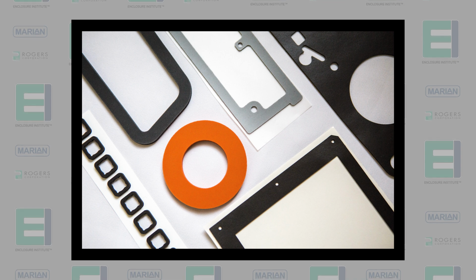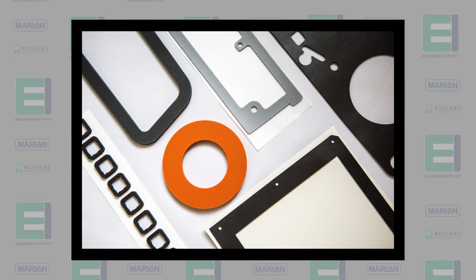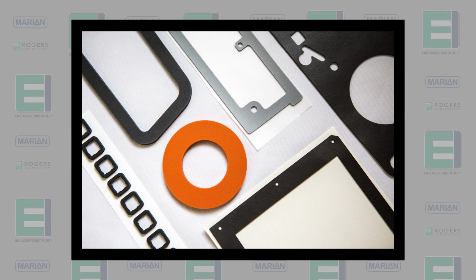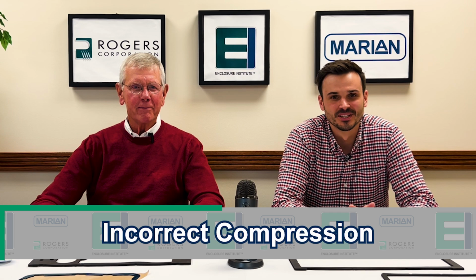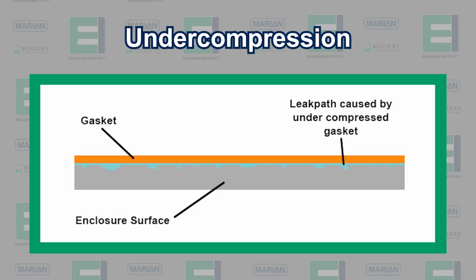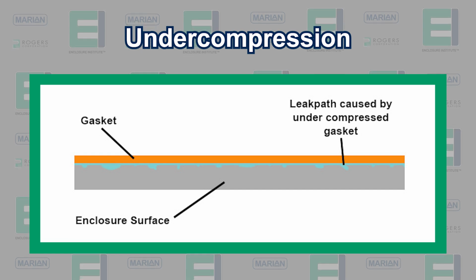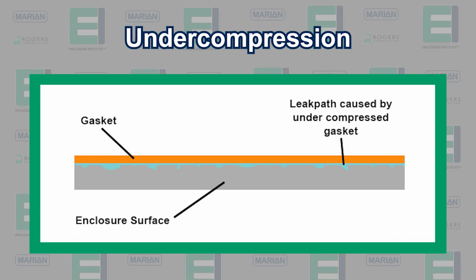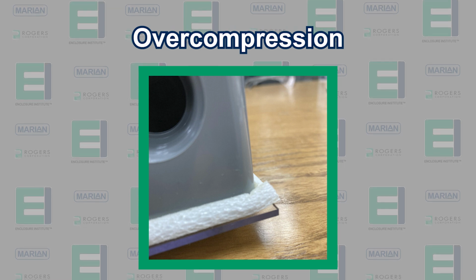Almost all gaskets provide a good seal when the new device is fresh out of the box, but over time, many seals fail prematurely due to one or more stumbling blocks in the material or the design. The first problem we'll discuss is applying too little or too much compression to the foam gasket. Incorrect compression, whether too little or too much, can lead to material degradation and a leak. Insufficient compression may leave gaps, while excessive compression can deform the material, reducing its effectiveness over time.